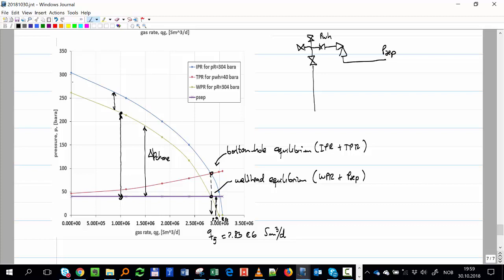With a compressor, right? The compressor gives energy and it's going to reach that. So if my reservoir engineer wants to produce 2.9 instead of 2.8, I say we have to install a wellhead compressor that gives me 20 bar to reach that. At that moment, the two pressures are not the same anymore.